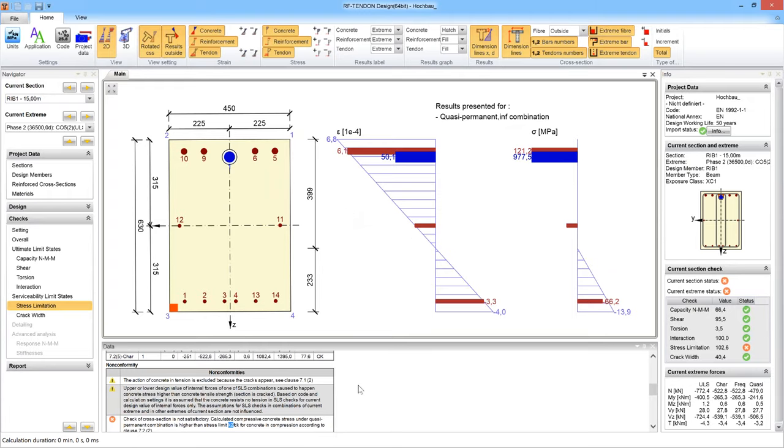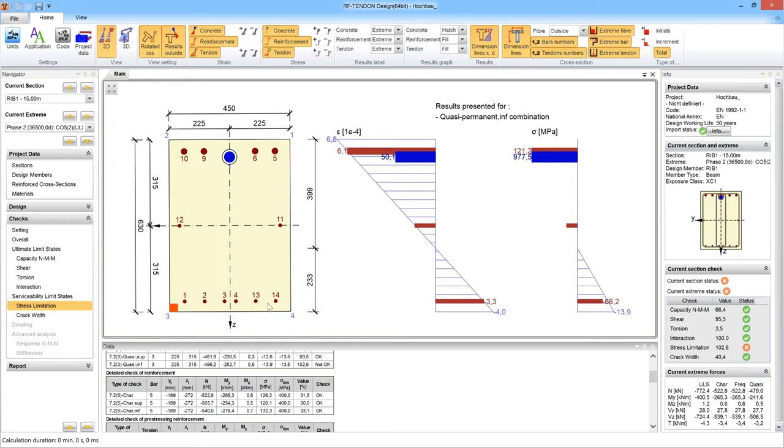But in this case, it is at the end, you can see that it is phased at 100 years. And in this case, either we say, okay, 2% is not that big a problem, or we would have to increase the depth of the cross-section, or we can also increase the concrete grade.